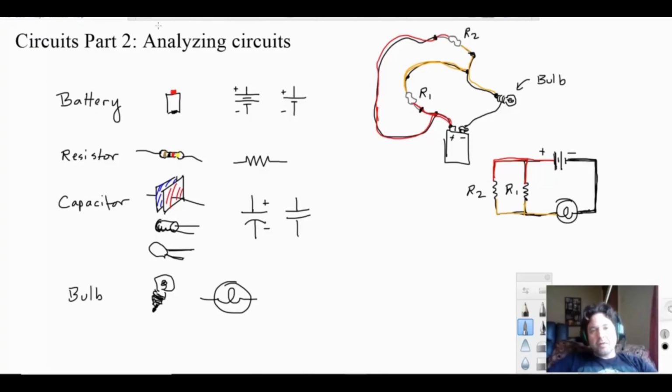That's one way to talk about that orange section. Another way to talk about that orange section is called voltage drop. So if we went from 9 volts on one side of our resistors to 6 volts, that means that we lost 3 volts, right? So we had a 3 volt drop. It is okay to say voltage drop. It is okay to say difference in voltage. It is okay to say voltage across.